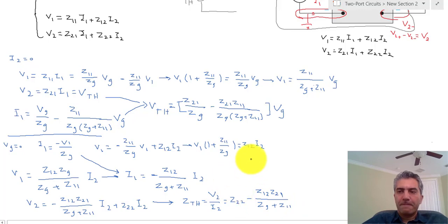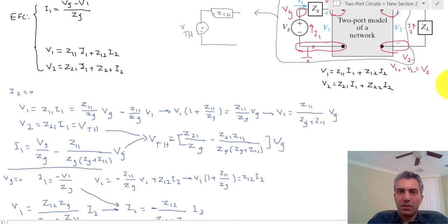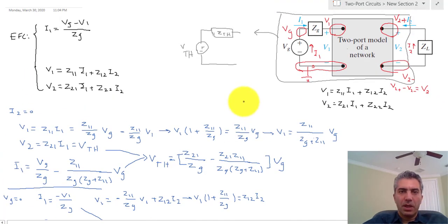So from these two I have developed the Thevenin model for the part of the circuit that we discussed. It's going to be hard to show both the circuit and the equations, but now I have these two values for my circuit. Now I can put the ZL back in, and this has simplified to a simple Thevenin model connected to ZL.